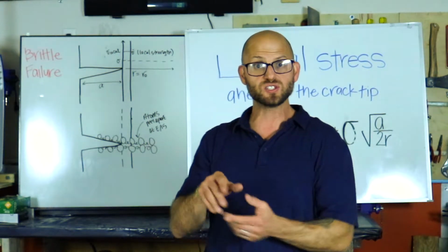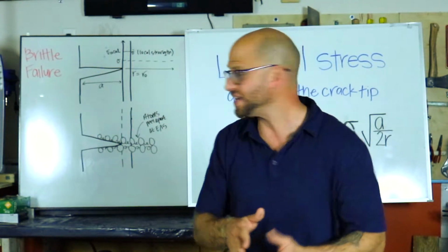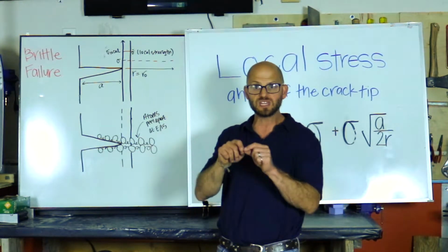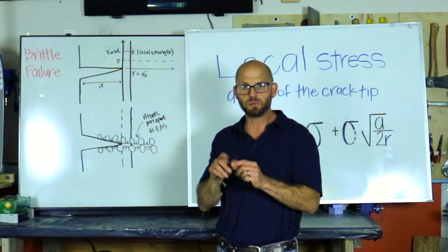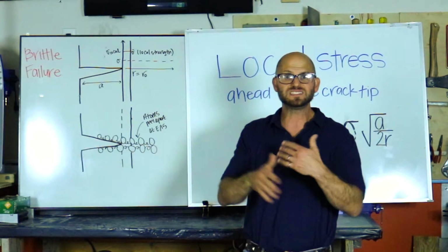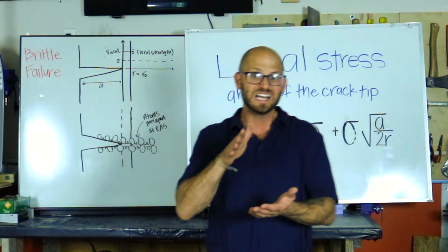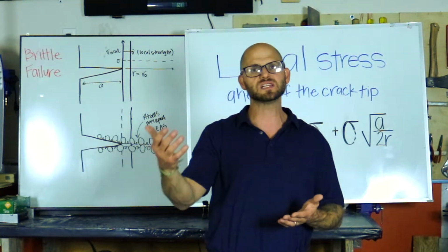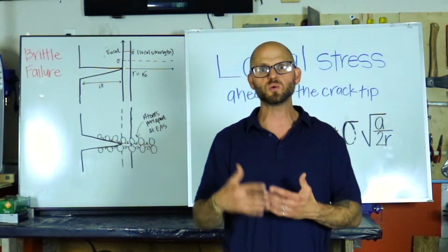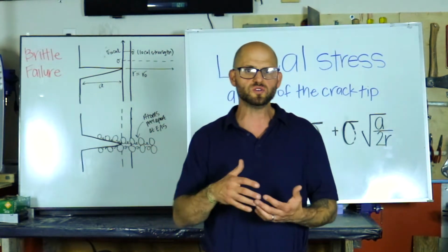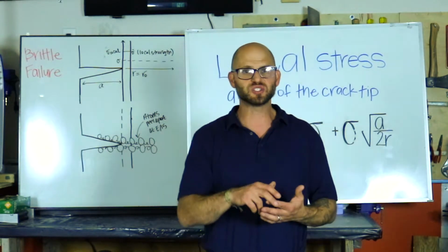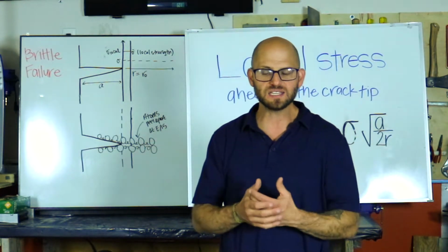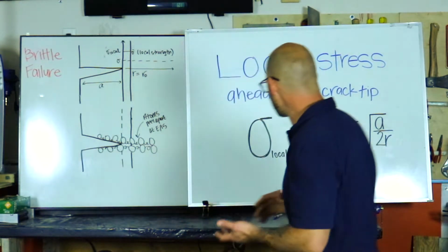Then that crack spreads so that it tears apart the interatomic planes like you see here in this rudimentary drawing. So first it's tearing apart the individual interatomic bonds, but then it spreads over to the planes until we have that smooth surface or that cleaved surface at an intermolecular space, but then that also translates back up to the macroscopic, and that's why we see that smooth surface with our more brittle materials like ceramics, glasses, and even concrete. So that's the theory behind it, and that's how we go from the microscopic up to the macroscopic.